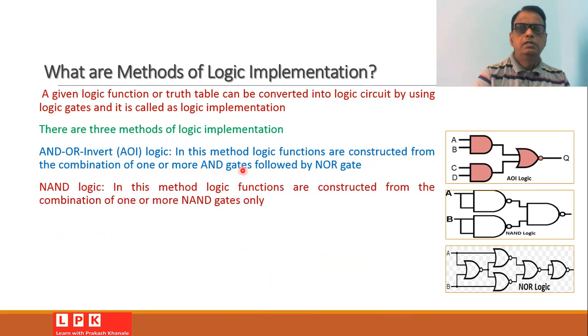Another method is to use only NAND gates. We know that the NAND gate is a universal gate, and therefore by using only NAND gates, we can implement any given logic expression. When only NAND gates are used for the implementation of any given logic expression, that is called NAND logic.